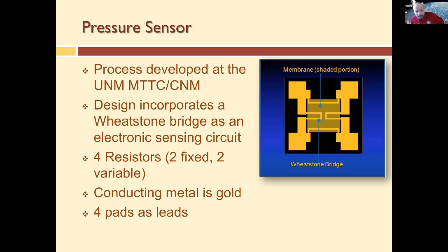Okay, and typically you can use different materials depending on what you're doing. So we used chrome and gold, right? Chrome is put down so the gold will stick to the silicon nitride, and we'll get more on that later. And it looks cool. But now we can use nichrome or just chrome, and we've done copper. So there's different materials you can use, and evaluate to see which works best for whatever application you have. Gold is nice because it's pretty inert, doesn't react with chemicals very well, so it can be exposed to the environment a little bit better.